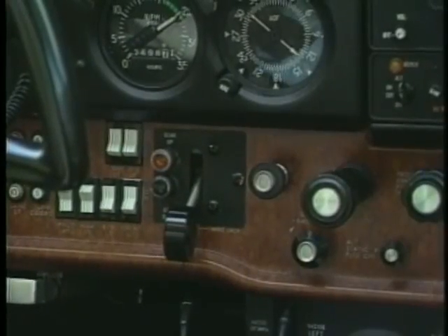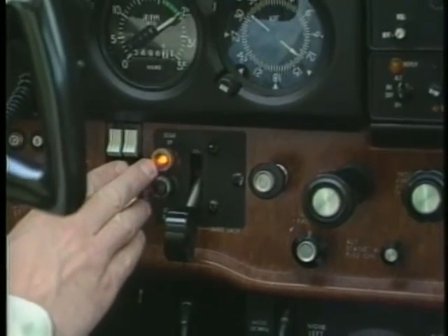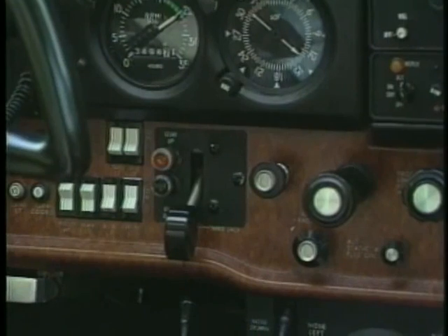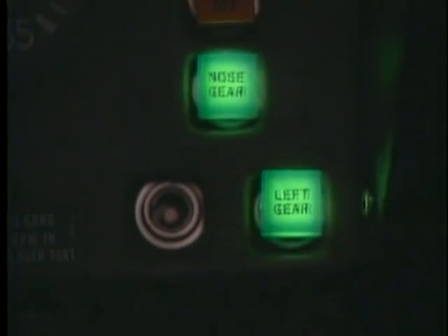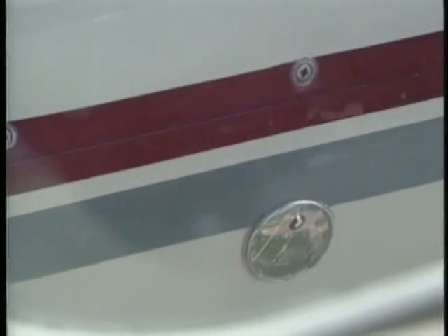Some landing gear indicator lights have a push-to-test feature, so you can quickly determine if the bulb is burnt out. Another way to determine if a bulb is burnt out on systems with more than one light is to switch the bulb with one that is already illuminated. Most systems are set up so that all of the gear lights are interchangeable. In this way, you can quickly determine if the problem is in the lights or the gear itself. Some aircraft also incorporate a small mirror to help you visually determine if the gear is down.